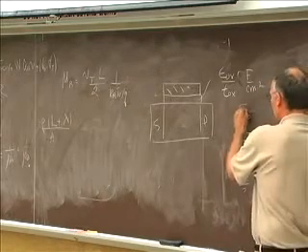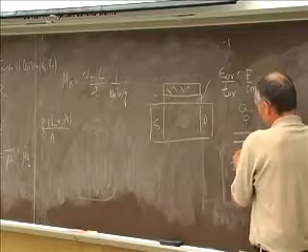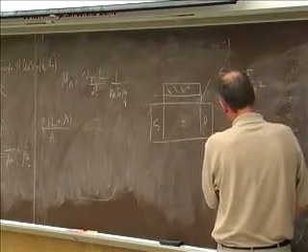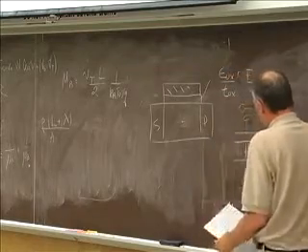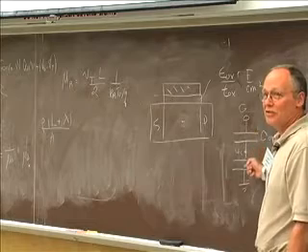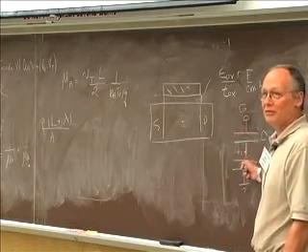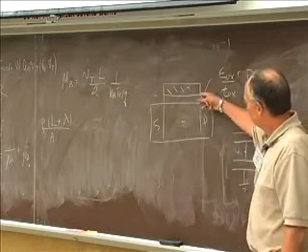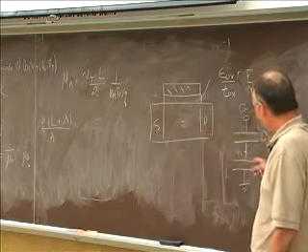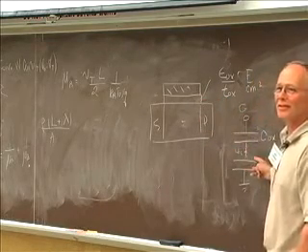So here's my gate terminal. Here's the surface of the semiconductor, or the middle of the channel. The actual gate capacitance is the series combination of two capacitors: the physical parallel plate capacitor formed by this insulator, and the capacitance due to the semiconductor.